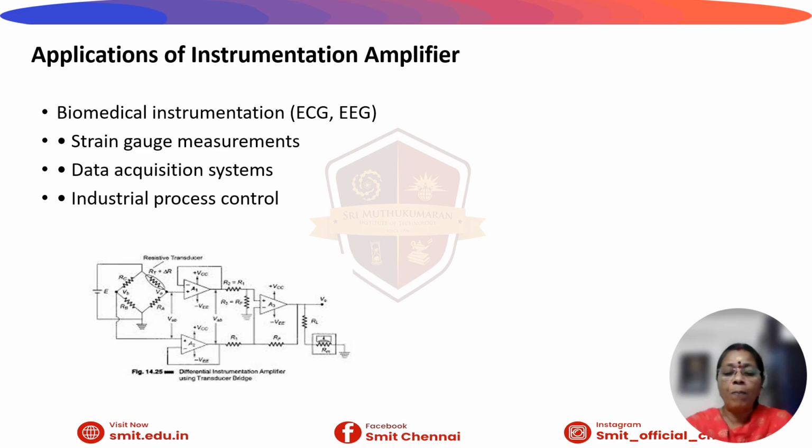The instrumentation amplifier's high common mode rejection ratio cancels this noise because it appears equally on both wires. We can scale the bridge millivolt signal to a 0 to 5 volt range suitable for the embedded system interface using Arduino or PLC by adjusting the single resistor RG. Thus, it is employed in instrumentation systems.